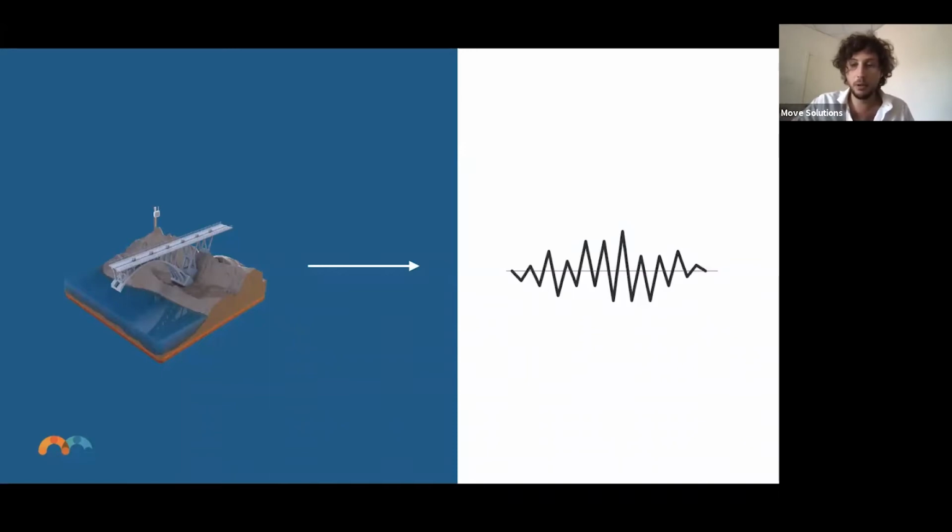So this parameter, how much force there is, can be related to, for example, the frequency, so how they vibrate. And on bridges, it's basically similar, okay? So vibrational monitoring, that is what it is called, is a really interesting technique, because from vibrational monitoring, I can get information about the structural situation of the bridge, for example.